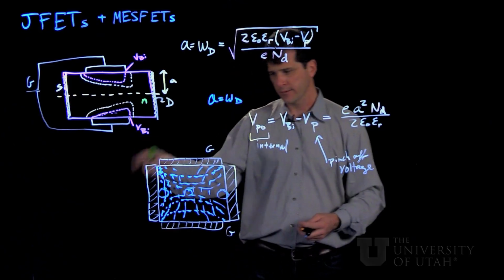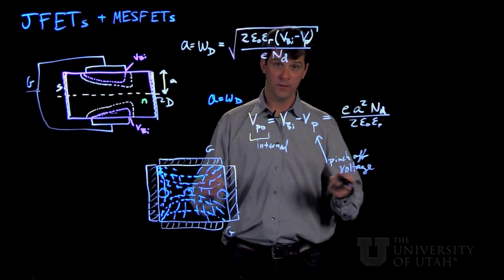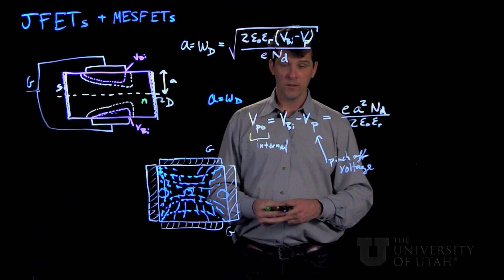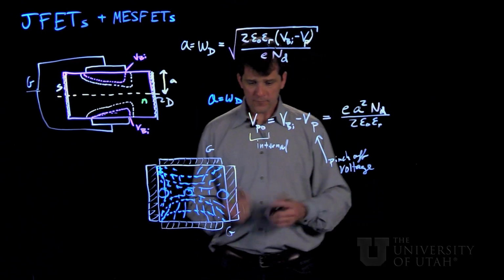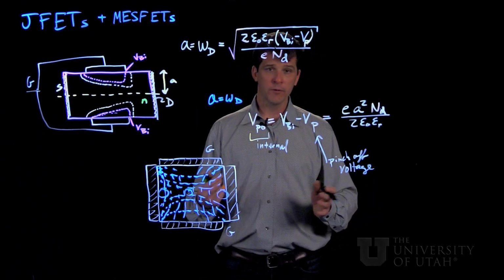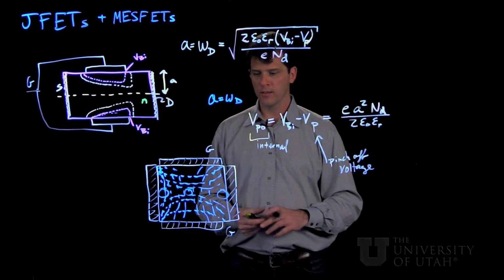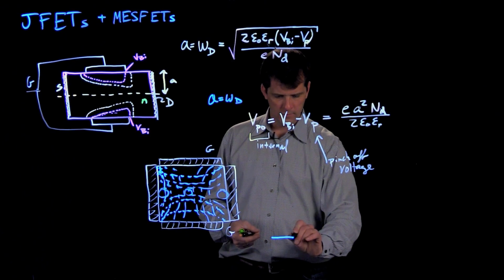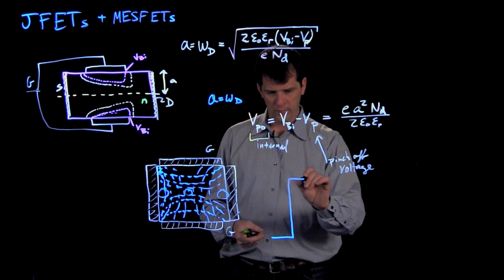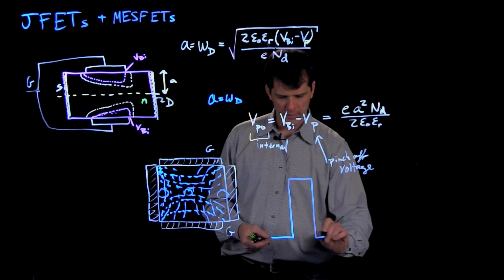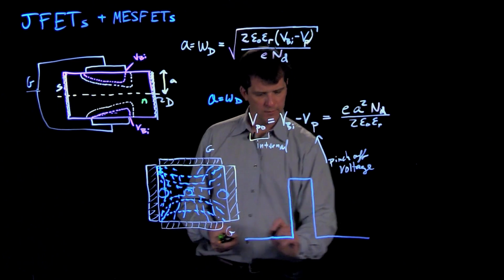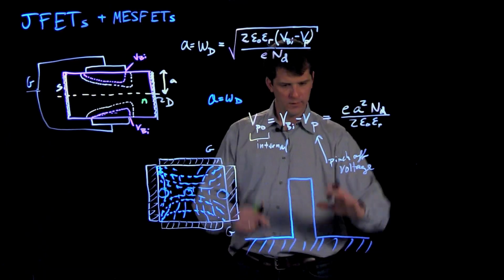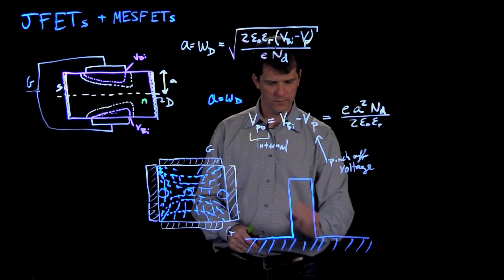Now it's hard to make such a freestanding transistor, especially in wafer-based fabrication. So the best thing that can be done is to get three gates around it. And this structure is implemented by etching a freestanding fin in the wafer. So all this here is the substrate, and we've etched down from the sides here, leaving this as our channel.